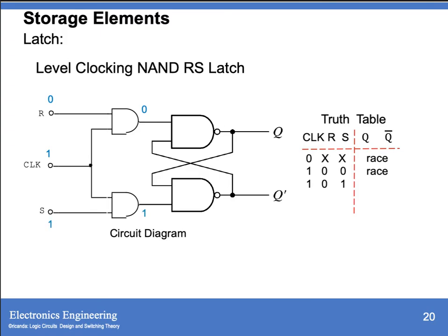If you have 0 and 1, the second AND gate will generate an output of 1. This will cause your NAND gate 2 to have an output of 0, and since it is 0, we have to NAND that 1 with 0, then we have a 1.